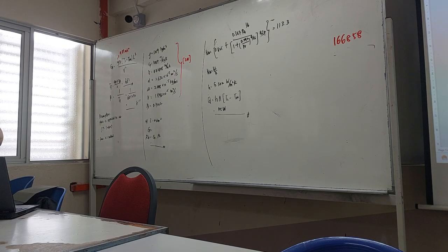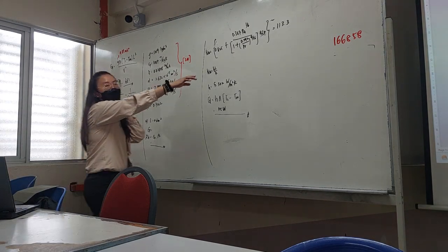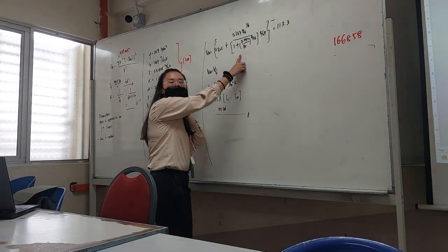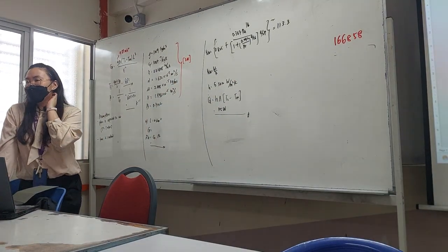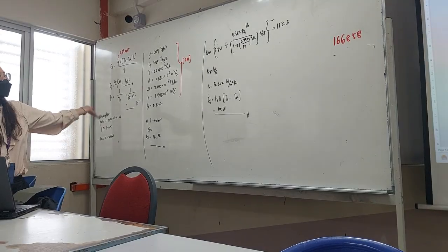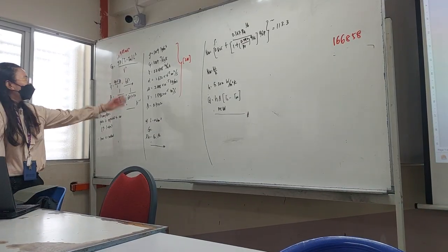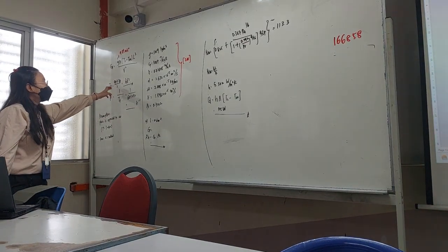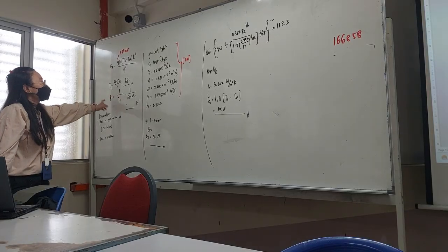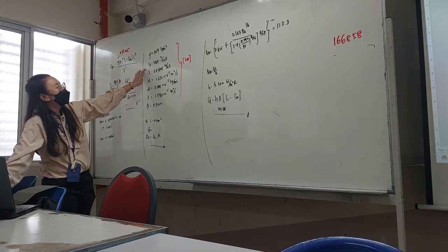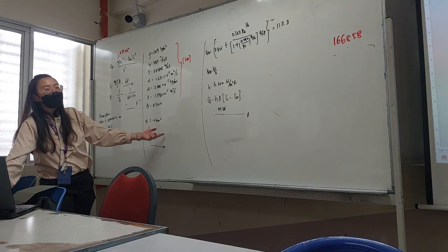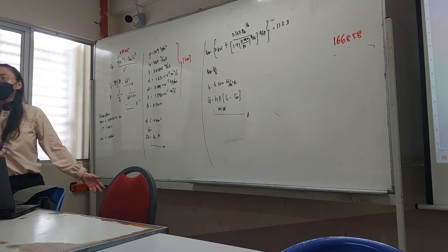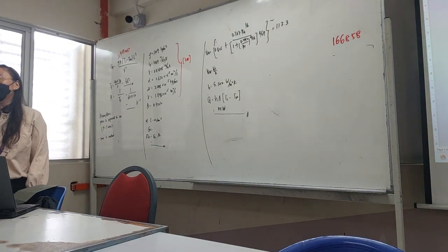This one I think is easy for you to score, okay? But with the conditions, you need to calculate correctly. Very simple. The steps are like this. Get the Tf from the temperatures. Then get the values from the property tables. Then you calculate the Nusselt number, get the h value, then the Q value.